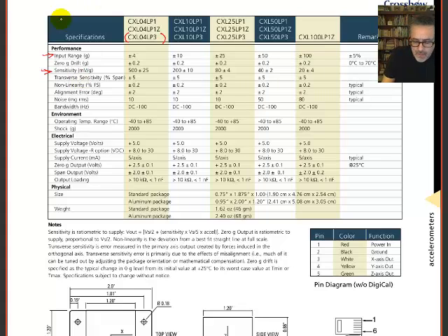Some of these you might not look at right away. It depends if they're important to your applications, but input range is important, sensitivity is important, alignment error, bandwidth. I'm going to talk quite a bit about that, and that's an important one when you're choosing. Bandwidth basically means the usable frequency range, and you hear the word bandwidth used a lot in many kinds of contexts, especially in communications. What's the bandwidth of a certain instrument? Obviously mobile phones and so on. But for us, note the units of bandwidth are hertz, frequency. This is cycles per second.